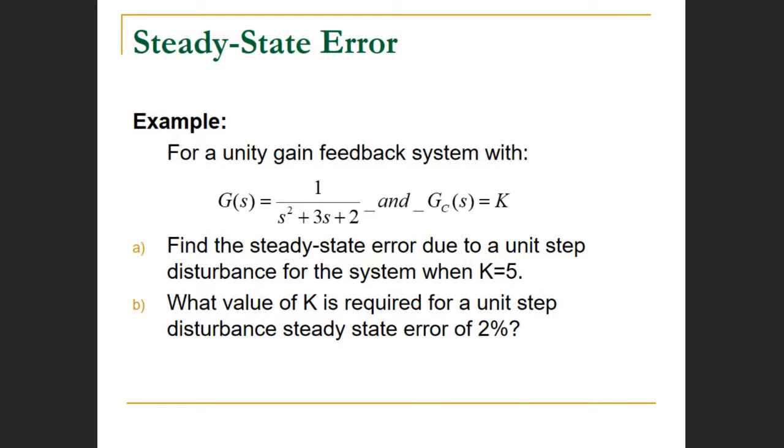And in so doing, it would introduce a disturbance. It's like a step disturbance. That camera has a weight. And when I say suddenly, I mean you attach it and release it. It's like a step disturbance where the drone is now going to be pulled down by a certain signal, which is going to be the weight of the camera. And so that's a step disturbance.